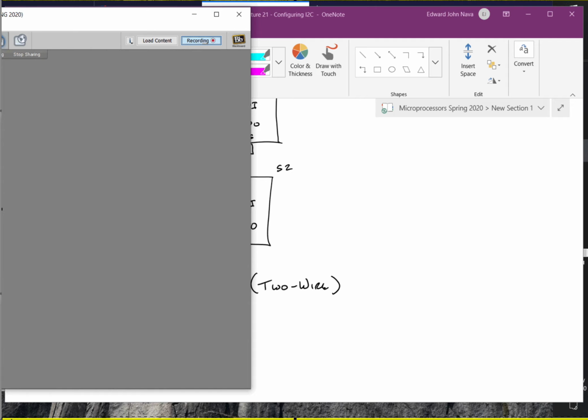So there are three main classes of interrupts distinguished by use case and ISR. So the interrupts are basically, you can set up interrupts for data being available to read. You may have a buffer that is empty that you want to continuously transmit data, or there may be error conditions to which you wish to respond. So you can set up any one of them or all of them as appropriate for your application. You have a lot of flexibility in terms of those interrupts.